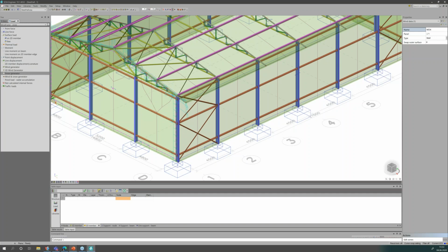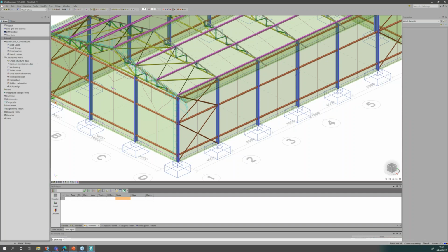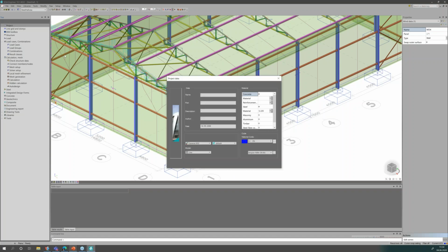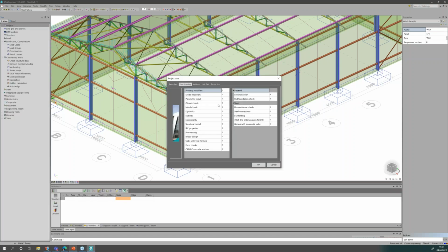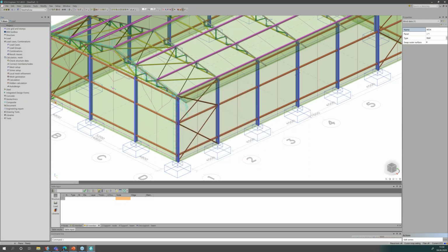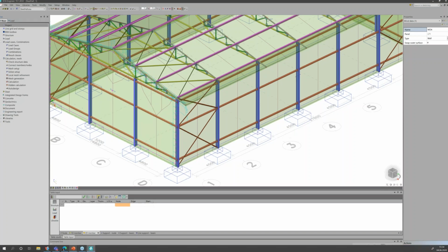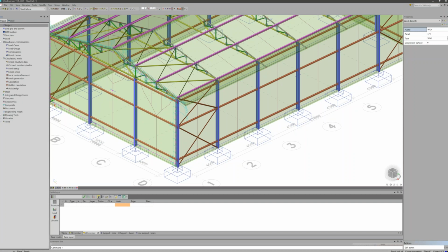If I haven't selected the climatic loads in the functionality, then I will not be able to see in the properties of the 2D member or load panels the option for 3D wind.